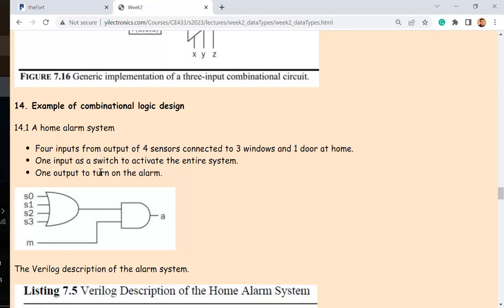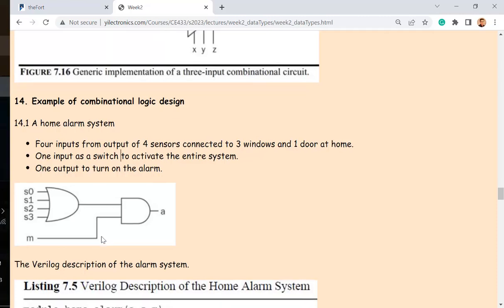It can be 1, can be 2, can be 3, it can be 4, but you have to output a 1 out of it. Okay, so it's an OR logic. And so what is this one doing? Yeah, it's like enable. So keep in mind, a lot of times we use AND gates with one of the inputs of the AND gate as an enable pin, so we can turn it on and off. Okay.